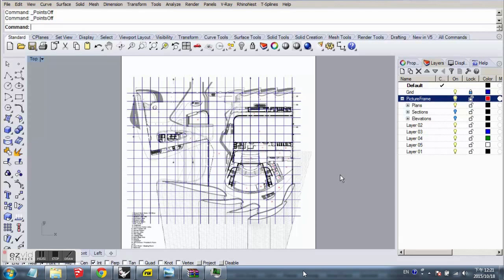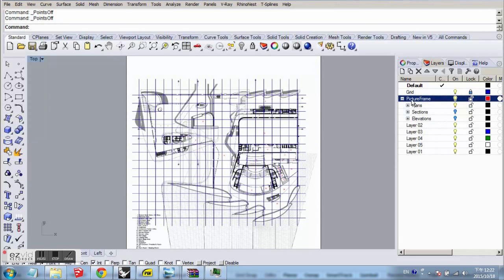We're going to start setting up some line work first for all the floor outlines, some important walls and the columns. Let's get started. Let's create some layers for our lines. Let's create a new layer and call it 2D. In this layer we'll put all our line work. Now let's create a new sublayer inside the 2D layer and call it 00 or ground floor level.